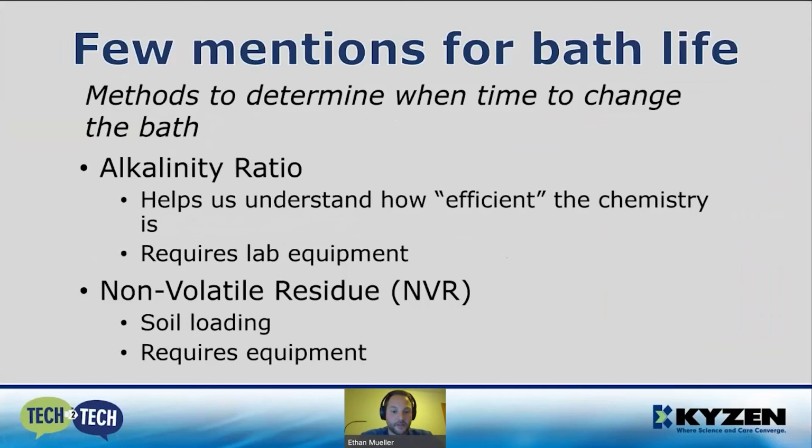There were a few tech to techs that we did do on this topic. So I would encourage you to go back if you are interested in learning about these specific topics and reviewing those tech to tech presentations in the library. But I'll just make a quick mention of the two tests that we do use for bath life. The first is alkalinity ratio, and that is essentially telling us how efficient our chemistry is when we add it into the bath. And this requires some specialty lab equipment, a burette and a pH probe. And then we have NVR, or non-volatile residue, which is going to help us understand soil loading. And this also requires some equipment.